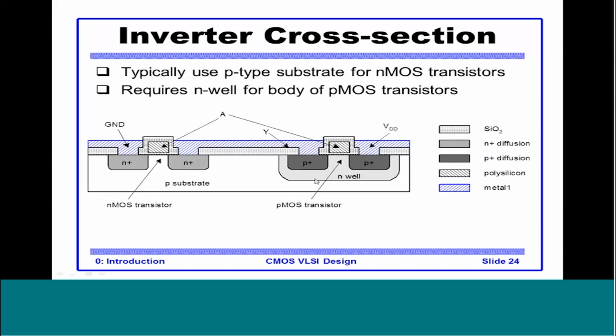Now the PMOS, on the other hand, would need an N-type substrate. So on the same p-type substrate, doping is done to make a region called N well. The N well acts as the substrate for the PMOS transistor. Again for the PMOS, for source and drain we need P+ regions, so they are formed here using the process of diffusion.